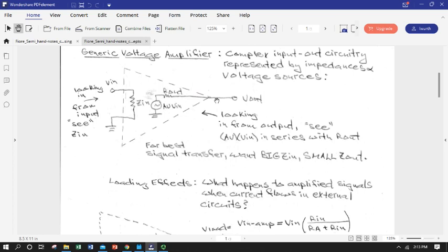And a way to think about this is your digital multimeter. When you're taking a voltage measurement, you want your meter to have a very high input impedance so you're not siphoning off much of your circuit current through the meter to make your measurement and thereby altering what you're measuring. That's analogous to your input impedance. You want that high.